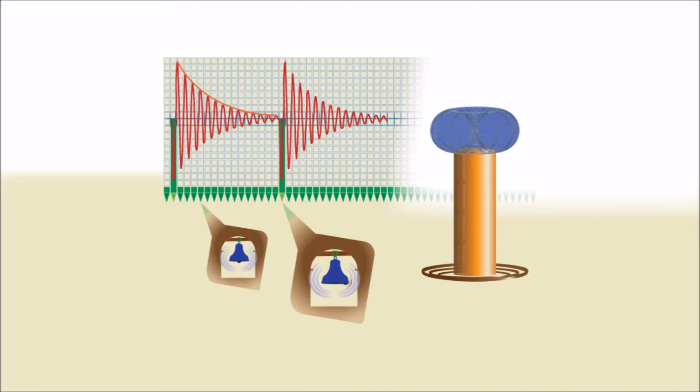So we want to hit the bell again with a clapper or strike our coil with a new amount of energy that builds up in the capacitor bank. But when we do this, we extinguish the existing oscillation. Unless you have superhuman capabilities, you will strike the bell with a clapper and extinguish the existing resonance of the bell and give it a new amount of energy to resonate again from the same magnitude. This does not result in buildup of energy, so you hit it, it rings, and then you hit it again and it rings.